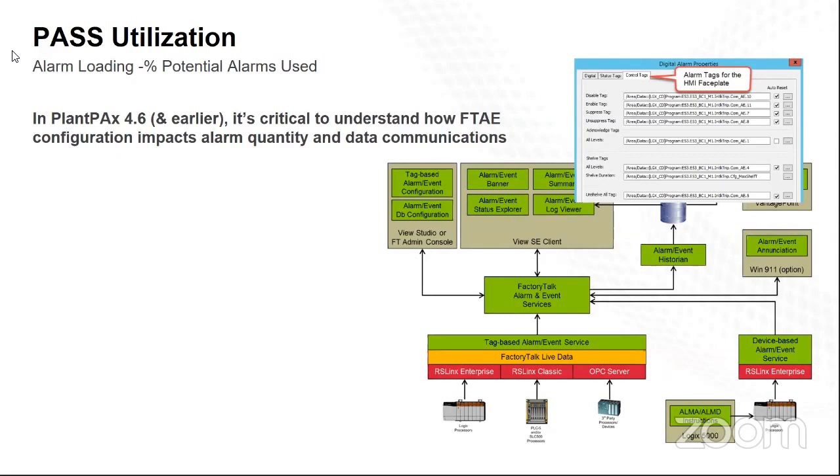That's one of the reasons in the process estimation tool that most people will call BS or something when they see it, because they see the number of alarm tags driven based on the IO count. And they say, there's no way I would ever do that many alarms. Well, in the real world, you wouldn't, but potentially that's what you could see, and we're designing to the potential.